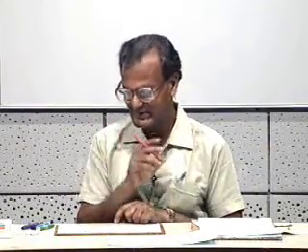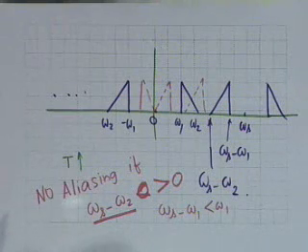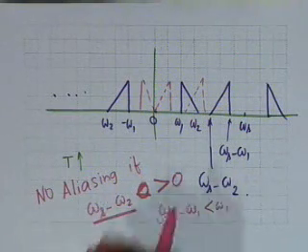And this is what is used in bandpass sampling. In bandpass sampling, you must realize that we cannot sample a signal at any given frequency that we want. After all, sampling involves an electronic circuit, and electronic circuits have a limitation on how high a frequency a given signal can be sampled. There is a limitation. You cannot sample at 1 gigahertz, for example. The stray capacitance will kill everything.